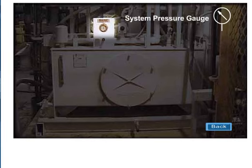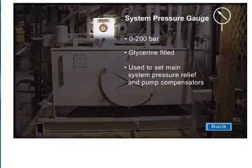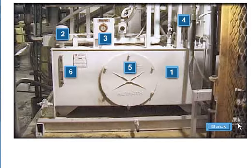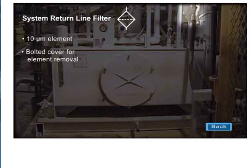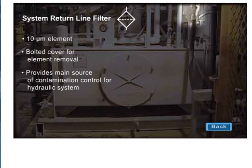System pressure gauge, 0 to 200 bar, glycerin filled. Used to measure main system pressure relief and pump compensators. System return line filter, 10 micron element, bolted cover for element removal. Provides main source of contamination control for hydraulic systems.